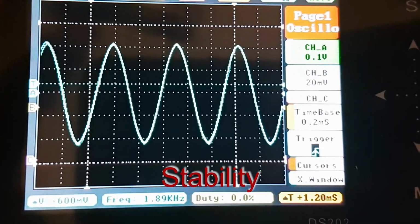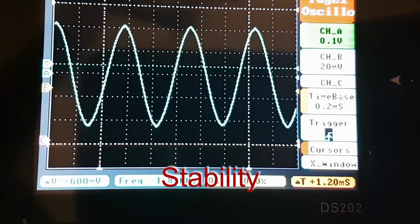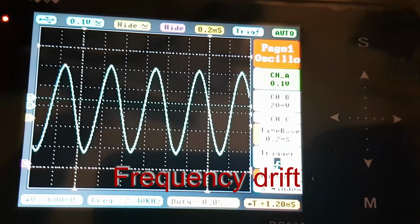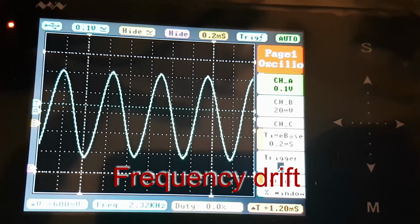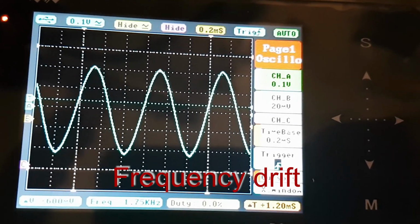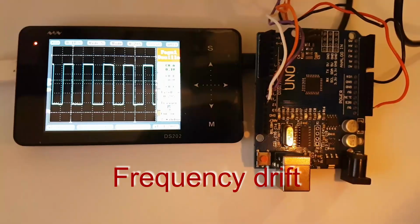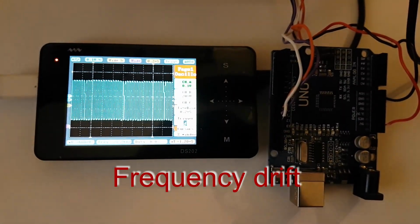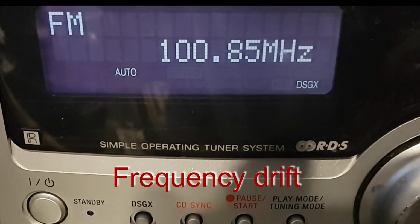When we use the term stability, we are referring to how the frequency may shift slightly up or down during a small amount of time. Here we can see the frequency wobbling on this waveform, but overall its frequency is pretty stable. Frequency drift, however, is how the frequency may drift off the desired frequency over a longer period of time. This could be a result of aging components or possibly an increase in ambient temperature. And this can be a real problem in applications such as radio. And if your radio ends up infringing elsewhere, that could be against the law.